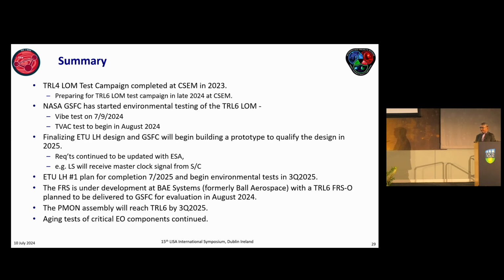Fantastic work. Thank you. One of the issues we had on LISA Pathfinder was that the temperature setting of the laser was very critical. What's the situation here? It is also critical. For example, the setting of the crystal itself determines the wavelength, and that has to be well controlled. We do have the thermal control capability to maintain that temperature. The pump diodes also, because you have to tune the pump diodes to make sure that it's absorbed by the crystal. So there are multiple thermal control loops within the main oscillator.